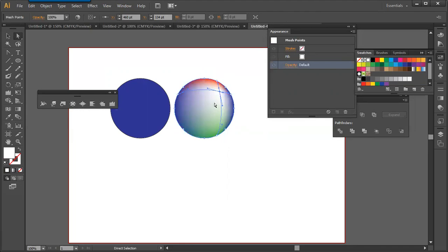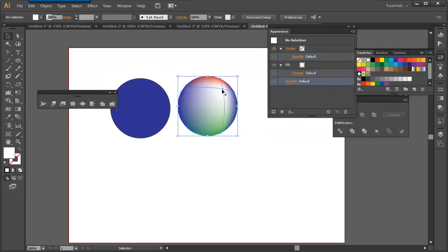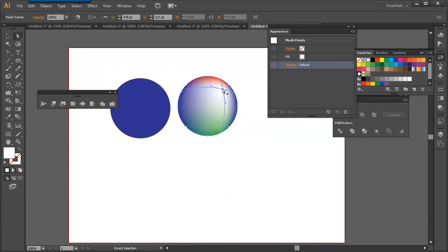So hope we have understood now how the color gets spread, applied and moved along with the point. Direct selection tool, select the point and move it. And color is not only placed on the vertex point wherever the cut is, but you can also place the color directly on the divisions. The time you click, it breaks the object into multiple divisions. We can place any color on any division directly, and that color will spread from that point.